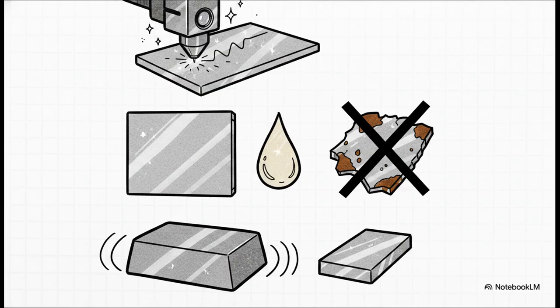First off, if you are sourcing reflective metals, think copper or brass, using older CO2 lasers is a disaster. They'll literally reflect the beam right back and destroy the optics. You must ensure the supplier uses modern fiber lasers. Second, surface contaminants like rust or oil totally mess with the laser's path. Top-tier suppliers use pickled and oiled, or P&O steel, to guarantee a smooth finish.